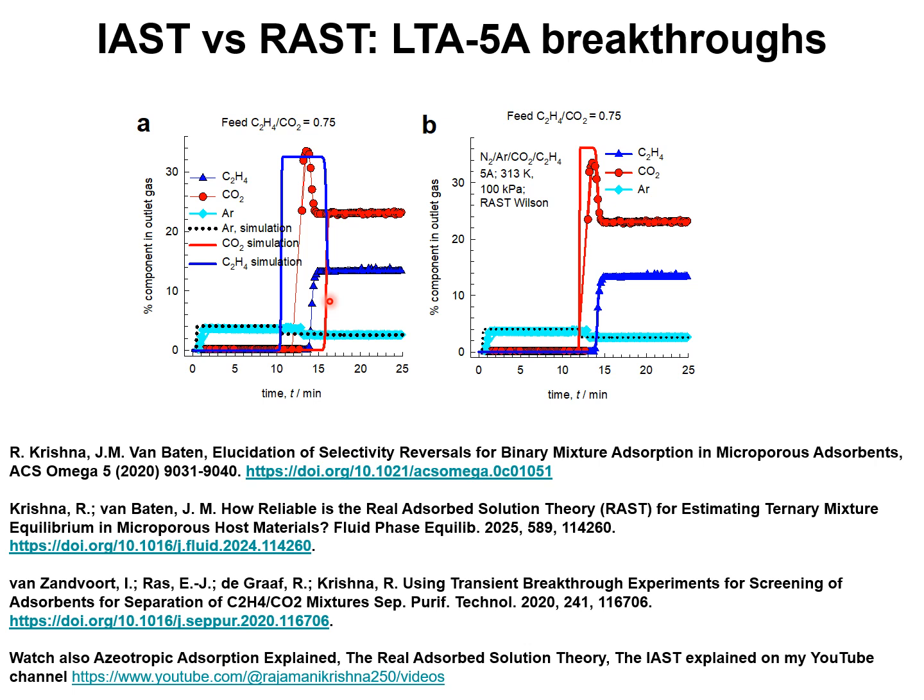So the IAST does not anticipate the selectivity reversal phenomena that is a characteristic of CO2 capture with cation exchange zeolites, as I have explained in several publications. 3 of these are listed here. You may refer to these publications for quantitative appreciation of the phenomena of selectivity reversals and why they occur.